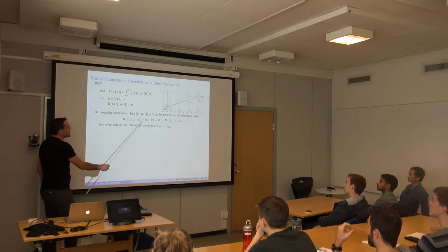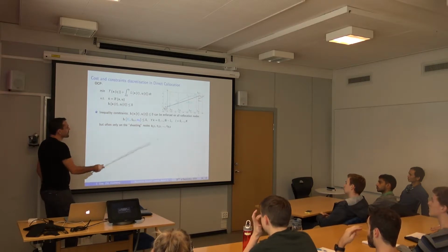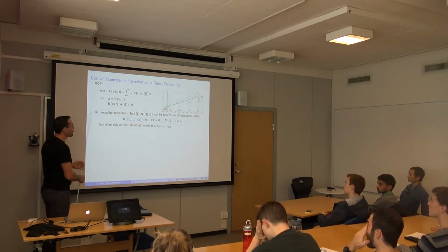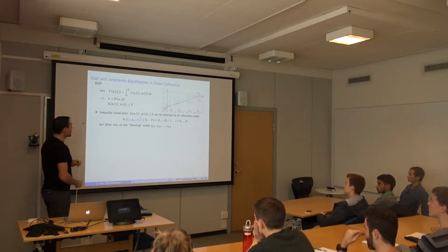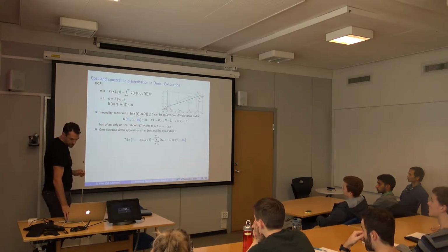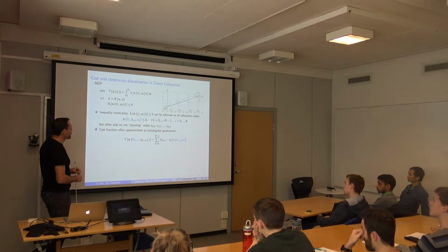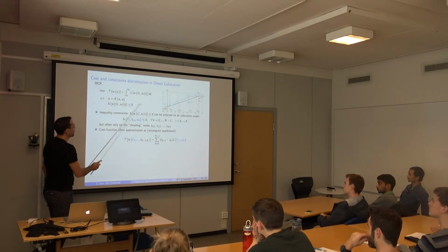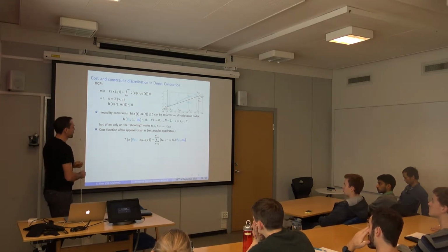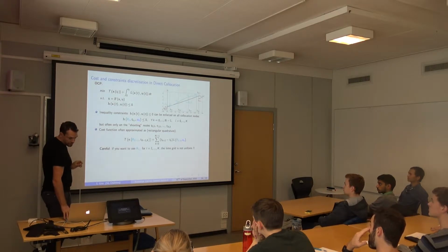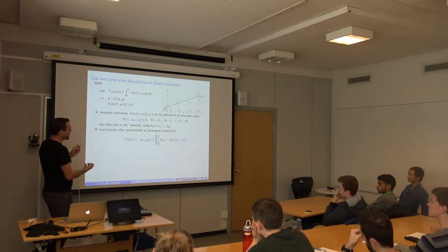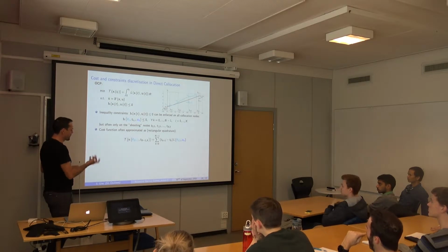And it's still a good idea to not have too many inequality constraints. Each new inequality constraint you add in the problem will tend to make it a bit heavier to solve. But in principle you can impose it on all these time points without doing anything special. Same story as what we discussed in multiple shooting. It's not uncommon to approximate the Lagrange cost by just some very basic rectangular quadrature. And if you want to make it more accurate, you can also carry the L inside the integrator, as we discussed in multiple shooting with the dynamic extension.